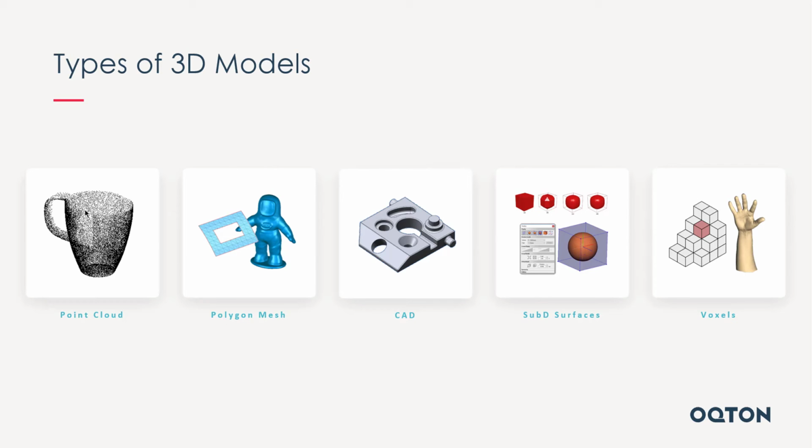The best way to describe what our software does is we will take these point clouds and we will connect those measurements together, the closest measurements together, into triangles. Like you see here on this image, that is the simplest way to connect those dimensions together, into the triangle form to represent the shapes. And what that inherently does is it's a smarter, more intelligent type of 3D model that then becomes a polygon surface.